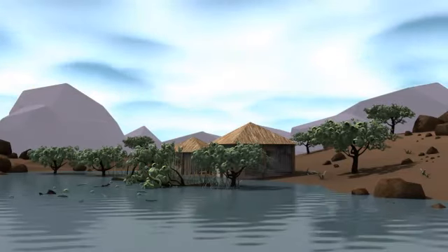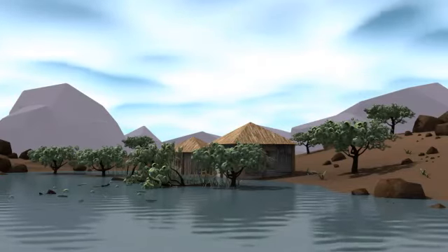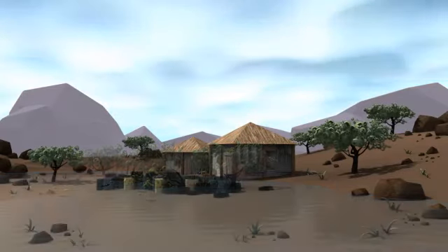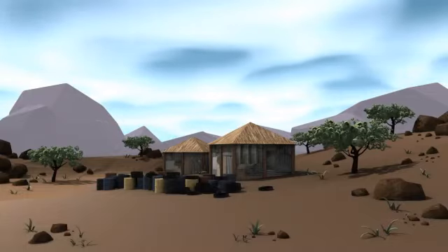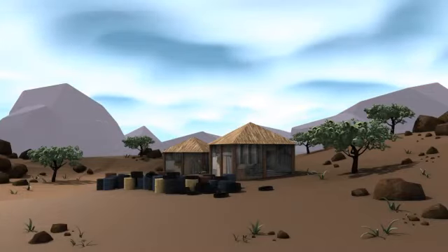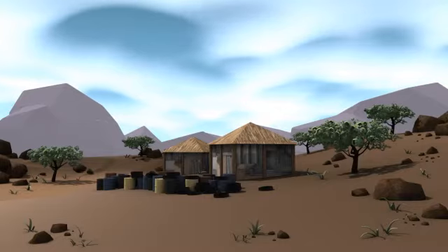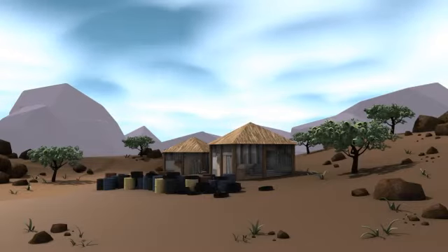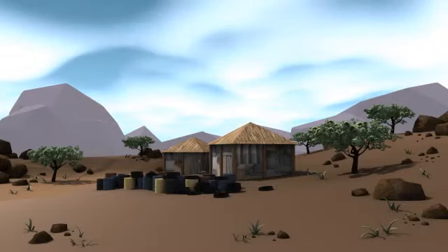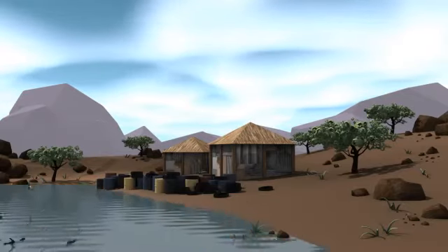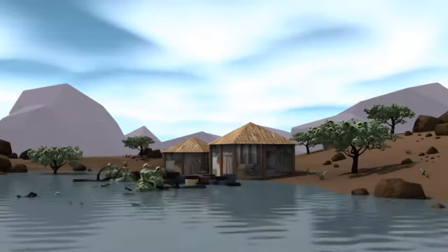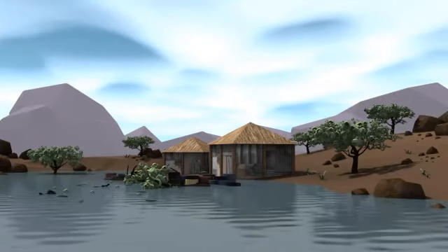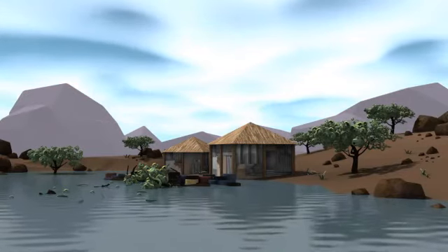If not possible to plant trees and use vegetation along the riverside, it is also possible to build protective barriers around the shelter. The use of recycled materials may be an option for this, such as oil drums or tires filled with compacted sand and laid in line. Again, although it may not prevent the water from reaching the shelter, this can serve as a protective action against more severe damage.